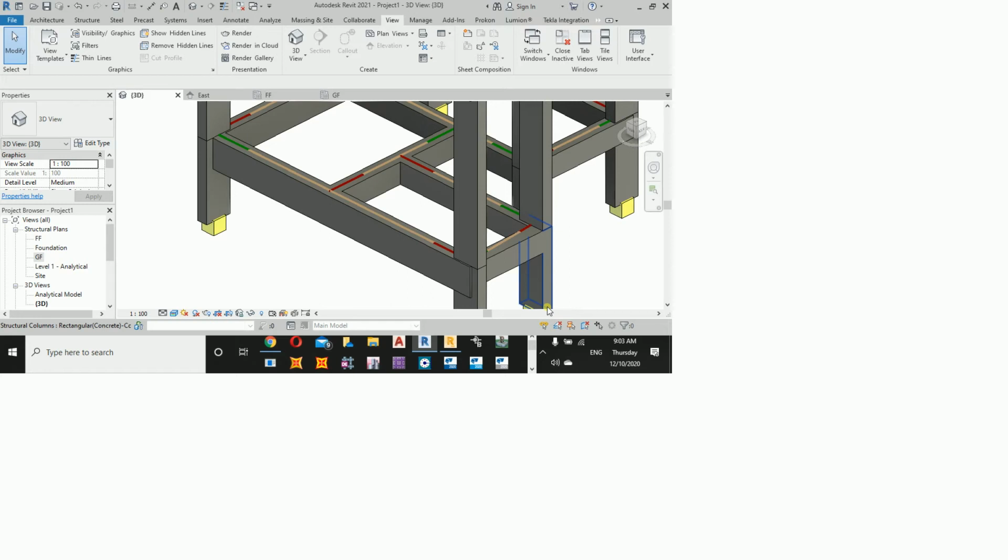If the structure is complicated, draw the beams and columns in Revit, send it to Robot, and draw the slabs in Robot. If it's complicated, Revit is not going to generate accurate slabs for you, and then you will have to modify them once again in Robot. So it's better to work the slabs over there.